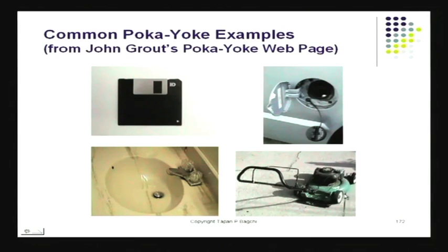Look at this lawnmower. Notice this bar. When you cut grass using this lawnmower, you're supposed to not just manage the handlebar, but also pull this bar and grip it like this. You're gripping two things together. You've got the handlebar, and alongside the handlebar you've got this bar also, and you grip the two together and hold it like this as you're cutting grass. What it really does, if you release the bar, either it will stop the engine or it will stop the movement of the thing. So it's a safety thing.